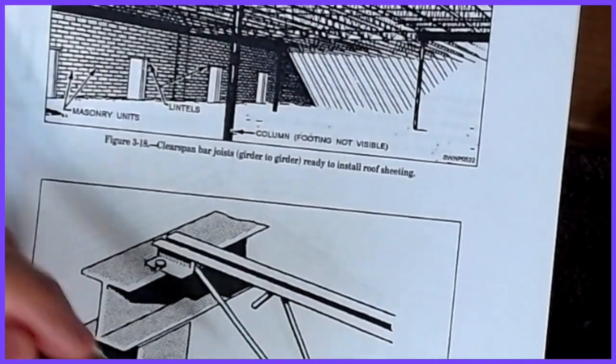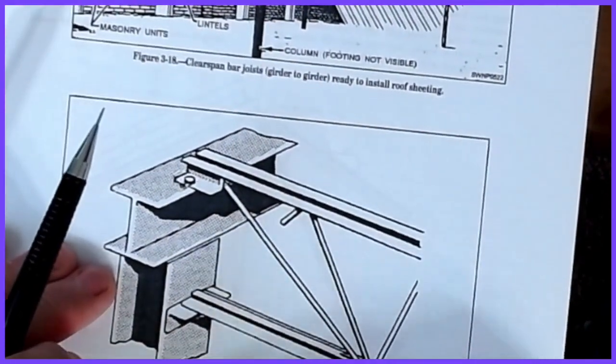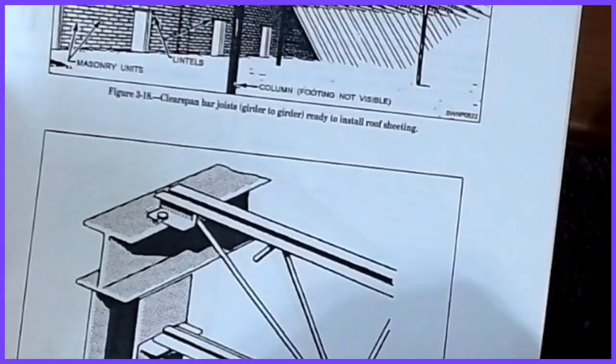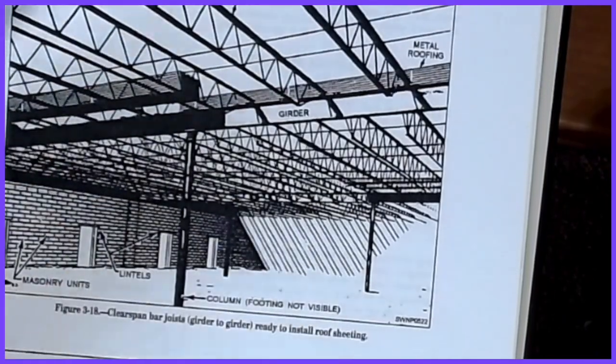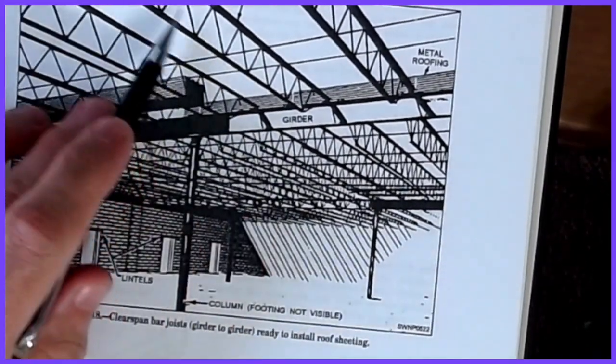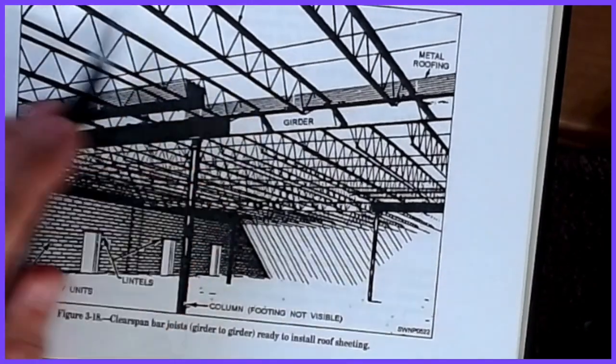But these are what we call bar joists or open web steel joists. They're basically trusses, and they come in all sizes. They can be very short, from 25 foot long, like maybe you see at Best Buy, to 40 feet, to even multi-span over football stadiums, and they're 12 feet deep. There are lots of variety, and that's the advantage of these, is that you can prefab any roof profile that you want. These are parallel chord, but you could have